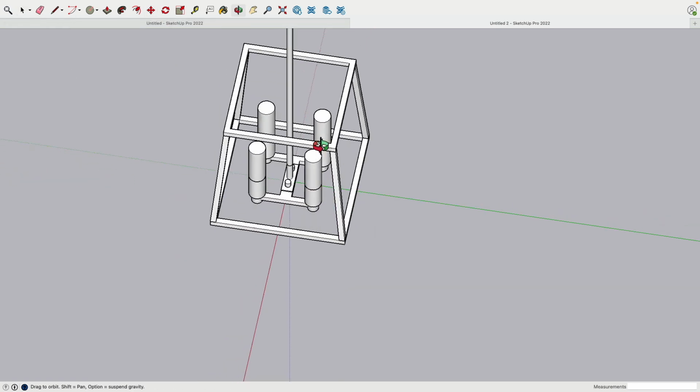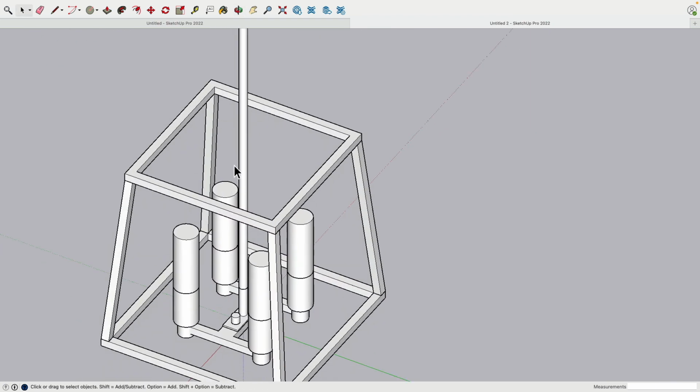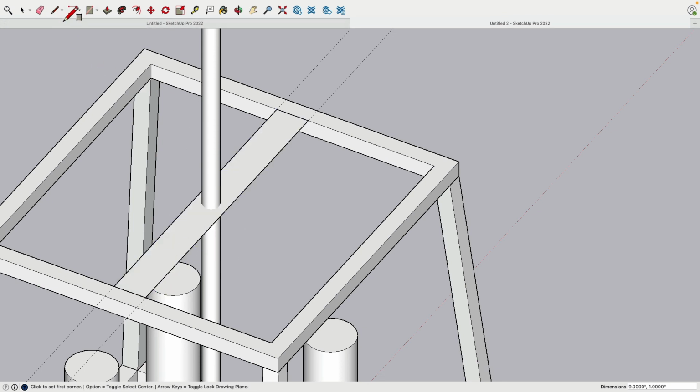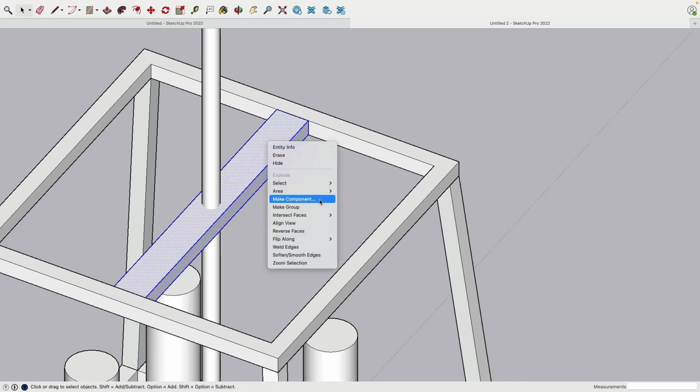So when we have this crossbar, it makes sense here on top to put a crossbar in. I mean, nothing actually holds this out of frame. So where's the midpoint? There to there. Thank you. I think 1-inch material will be good. So we could use the guideline 0.5, 0.5. Then this line I delete. Click, click, push down, click, triple click, and make a group.